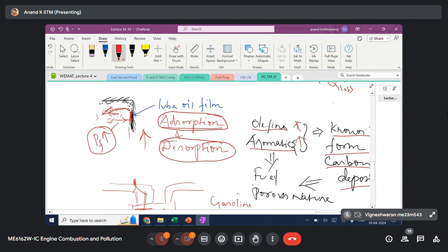So there is a backflow of this trapped fuel vapor into the cylinder. That is, it is going into the burnt gases, not into the flame. So only with a flame can you burn or combust this mixture. Since the flame is already quenched, only burnt gases are present. Only in that period of time is there a backflow or reverse flow.